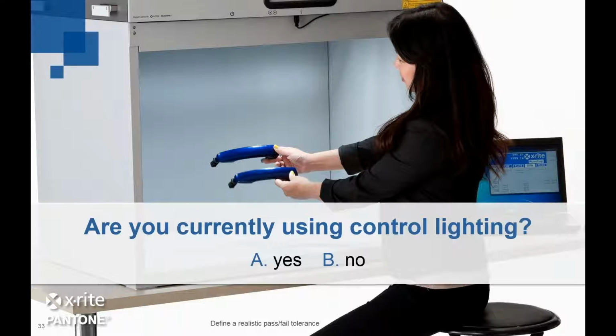For the other 5%, I would strongly suggest that you consider introducing controlled lighting. Many companies will do that by buying a light box. Some will go on a slightly grander scale. For example, the automotive industry will have color harmony rooms, which are really a large room that becomes a light box into which you drive the car, and you can do all the visual color checks within that room.